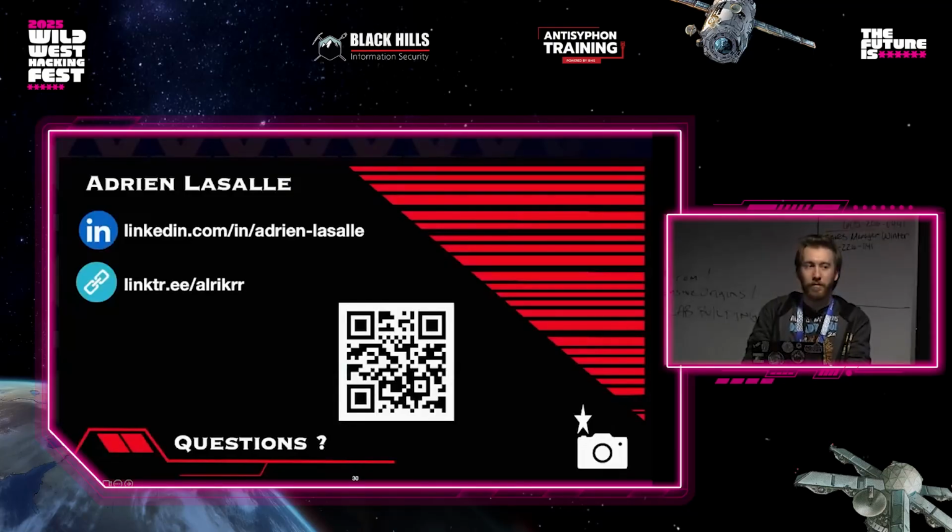No more questions? Simple one. Is there in KiCad a difference on the schematic between surface mount and through-hole components? So he asked me about the difference between surface mount and through-hole on KiCad. No, it's going to be the same. Maybe the PCB editor will be different for the component parts, but it's going to be the same process.